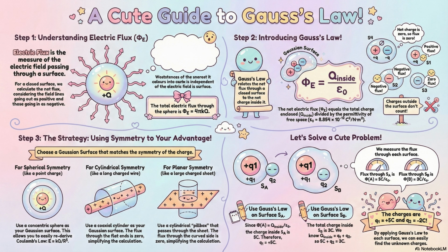It's a killer. Just as a quick practical aside, the source material reminds us that resistance is still often encoded with color bands, that old IEC standard. Like green, blue, red, gold is 5.6 kilohms, 5% tolerance. The abstract physics eventually gives way to a color code. Yeah, which brings us to the component where all this collides, the capacitor.